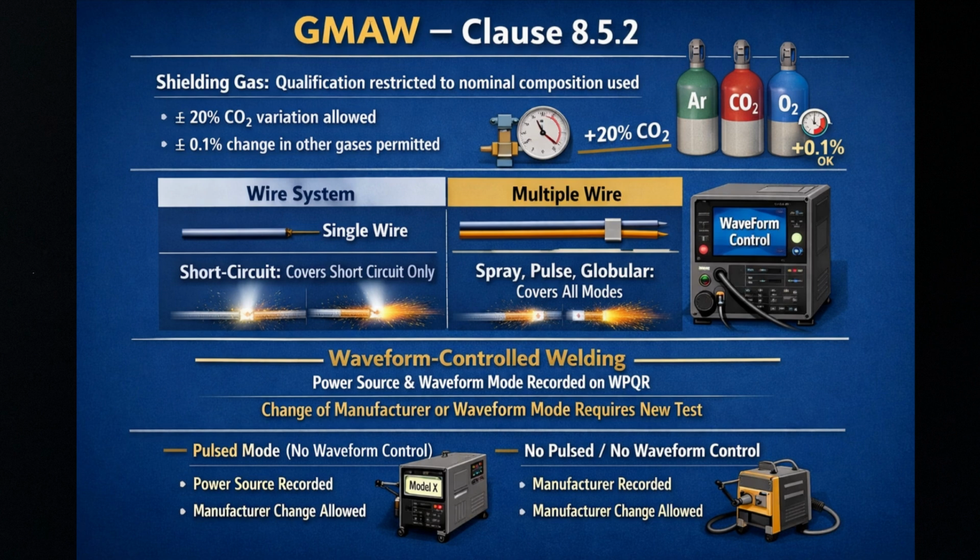For pulsed mode without waveform control, the power source manufacturer is recorded but a change of manufacturer does not require requalification. Similarly, for welding without pulsed mode and without waveform control, manufacturer identification is required but a change does not trigger requalification.